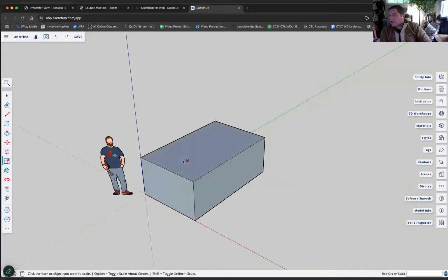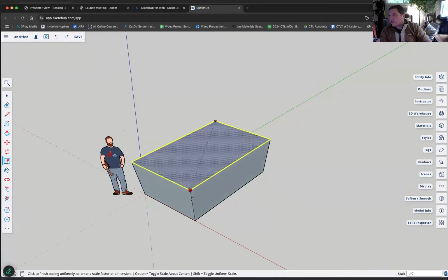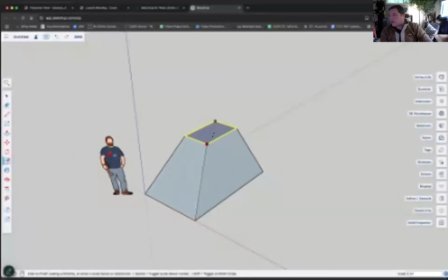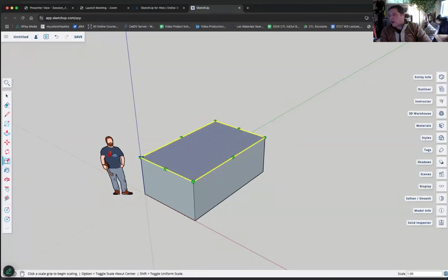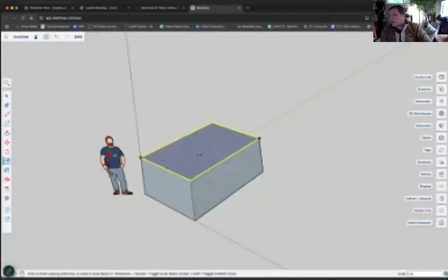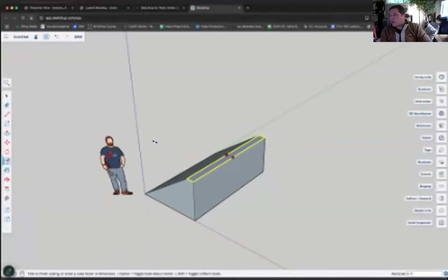This is one that allows you to change the scaling of the shape by going like this. This allows me to make a pyramid. This allows me to make kind of a rhombus shape. It's called the uniform scale tool. When I do this, it allows me to scale everything on a single plane. So you can see I can grab these different handles here and maybe make the pyramid go this way, or make the pyramid go this way. Now it's more of a ramp.